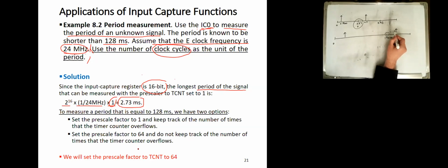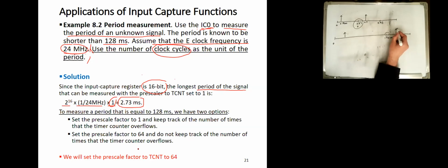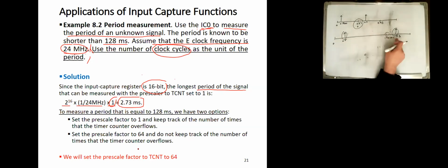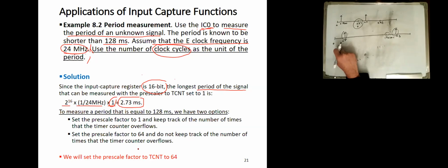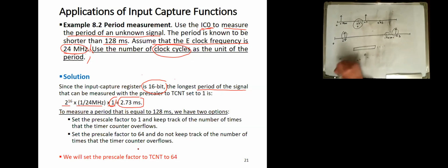All you need to do is to subtract this minus this. You will tell me this time might be less than this. For example, this might be 0.3, this might be 0.5. So the time will be minus 0.2. But technically, we are not subtracting like this when it comes to subtracting binary, because we are talking about a 16-bit timer, it is modulo subtraction.